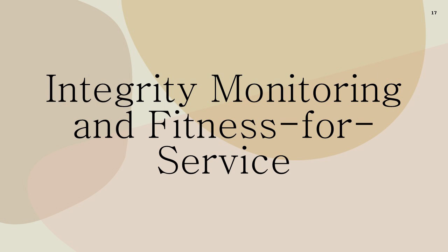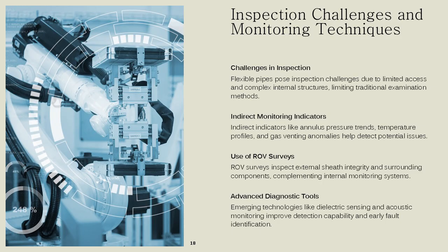Inspection challenges and monitoring techniques, residual risk and fitness for service decisions. Inspection of flexible pipes is inherently challenging due to limited direct access and complex internal structures. Traditional non-destructive examination methods are often impractical, necessitating reliance on indirect indicators such as annulus pressure trends, temperature profiles, and gas venting anomalies. Monitoring systems integrated into end fittings provide real-time data on internal conditions, enabling early detection of abnormal behaviors. ROV surveys complement these techniques by assessing external sheath integrity and ancillary components.